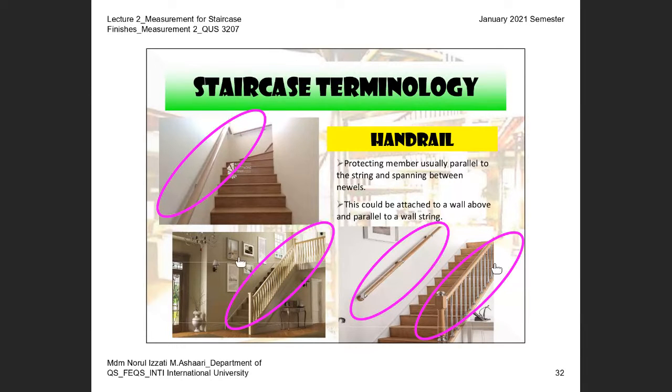And this is the design where you don't see any handrail bracket because the handrail is only on one side. Where you have a staircase that is covered on both sides with brick wall, normally one side must be installed with the handrail, where this handrail is installed with the handrail bracket.